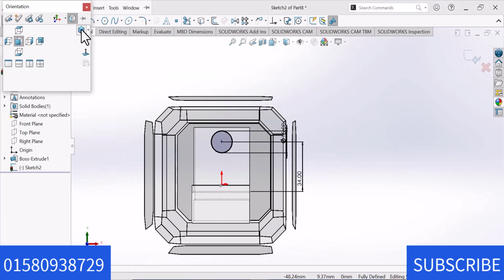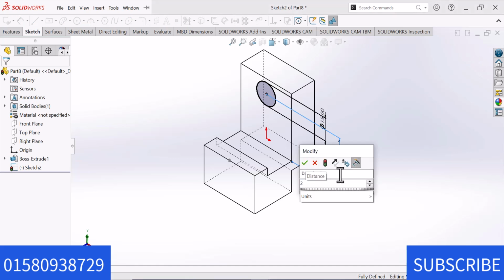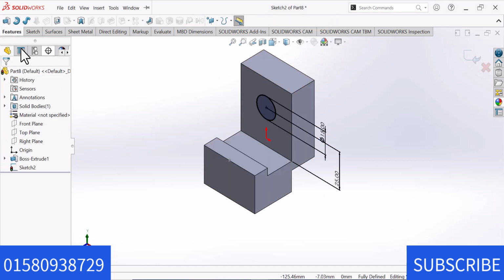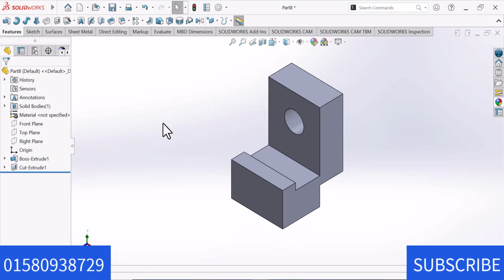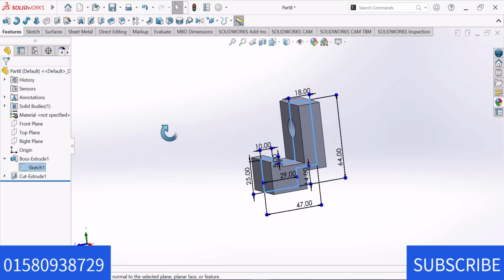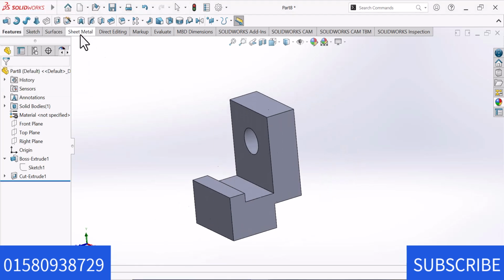Now go to isometric view. Now here give the value 25. Okay. Now go to Feature and select Extruded Cut. Okay. Now I am going to check the sketch, all dimensions below. Okay. Now go to isometric view.